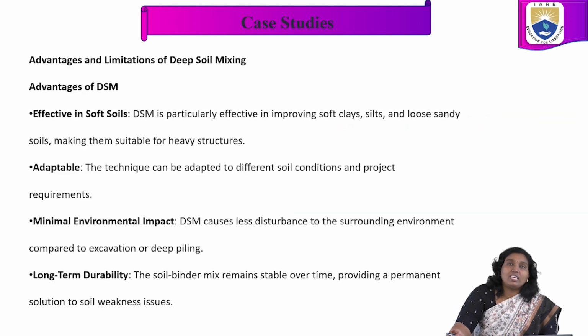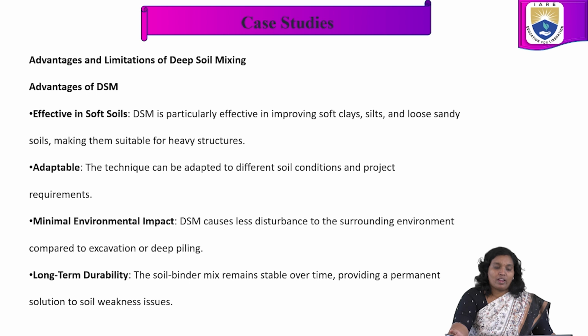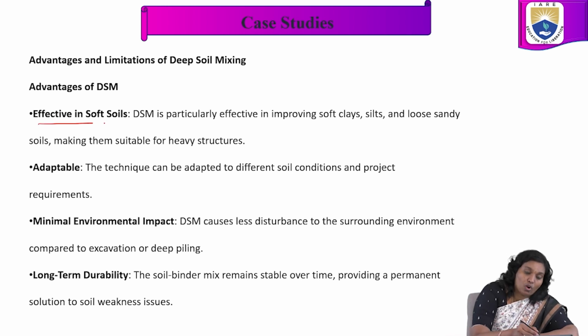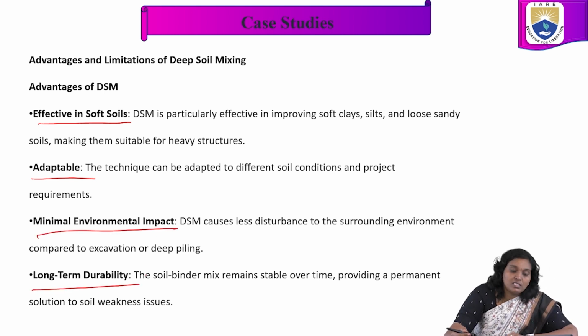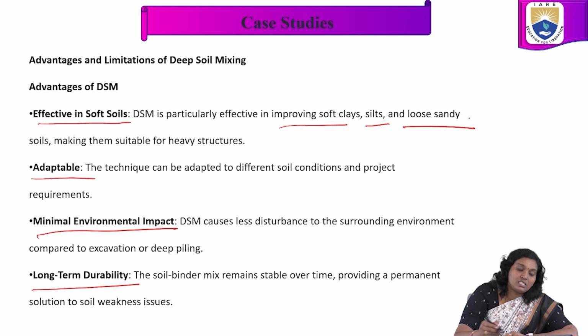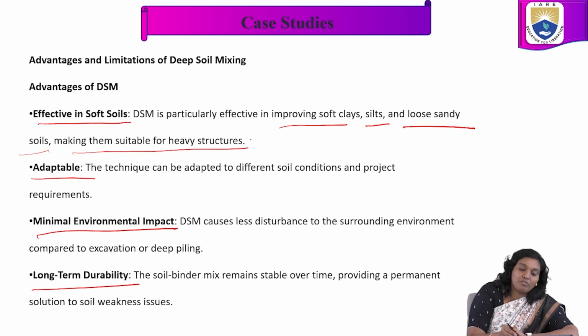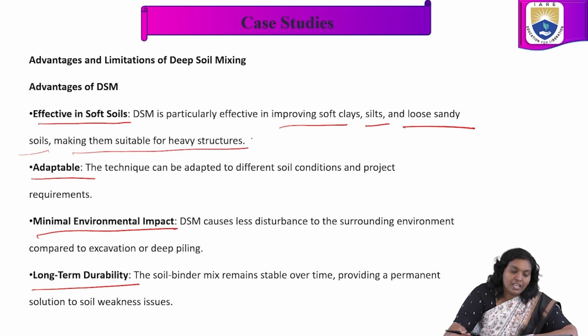In the advantages and limitations of deep soil mixing, deep soil mixing is effective in soft soils, adaptable, has minimum environmental impact, and long-term durability. So deep soil mixing is particularly effective in improving soft clays, silts, and loose sandy soils, making them suitable for heavy structures. It is adaptable: the technique can be adapted to different soil conditions and project requirements.